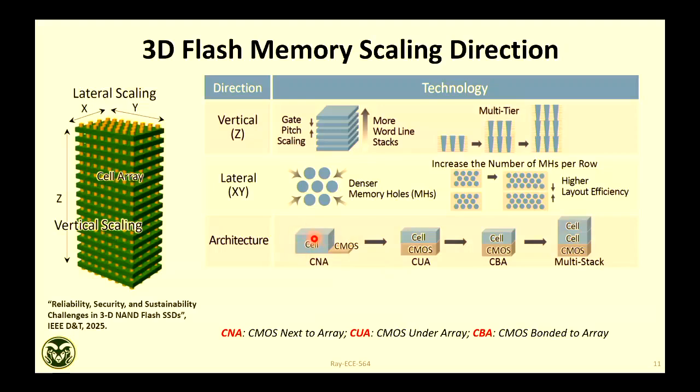In a typical chip, right? When I was working at SanDisk, for example, we had this structure. Your cell area used to occupy 80% of the die, and 20% of the die area used to be CMOS. Because your CMOS, or silicon, is at the bottom. Your CMOS circuitry has to be made on the silicon wafer. So that's why this is the CMOS.